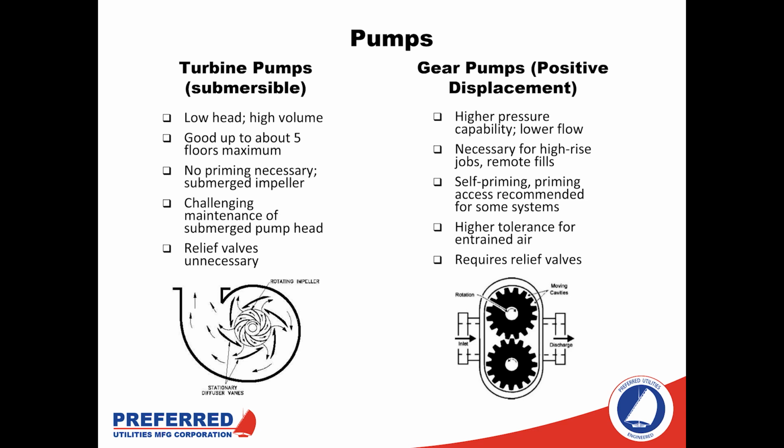Now, with the submersible pumps, one of the advantages is that having a relief valve is not as necessary, and this is an important safety consideration for our positive displacement pumps, where if someone was to deadhead the discharge, we need to make sure that we have relief valves that are going to discharge that excess fuel and relieve the pressure. And one note that I would make here, when we're talking about critical safety components, there are two different styles of relief valves that can be used on a system. There's the internal relief, which is installed directly in the pump head, and then there's the separate relief valve, which is piped onto a skid.